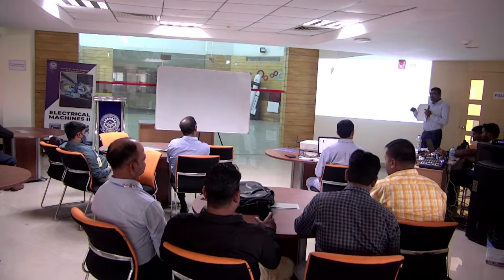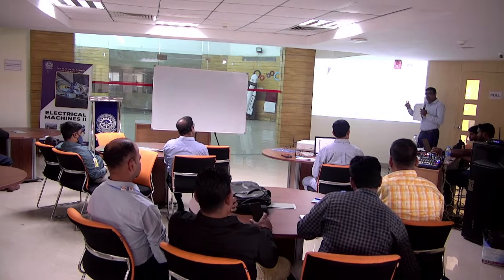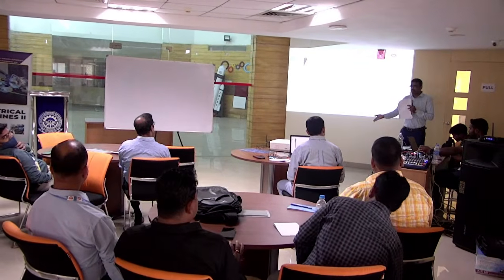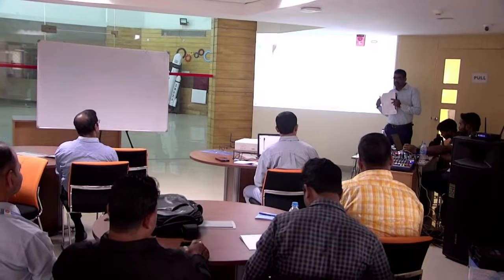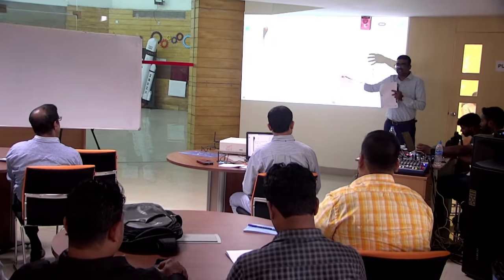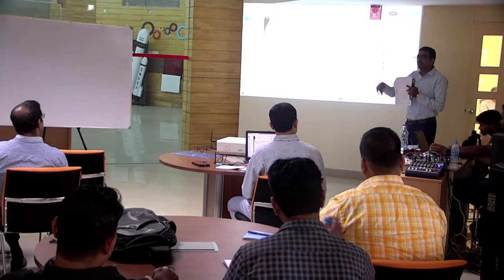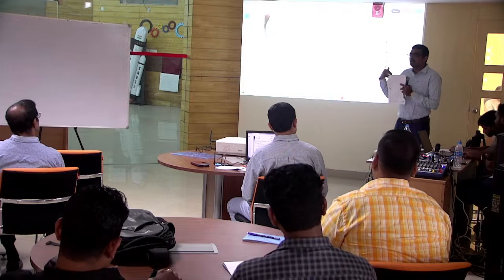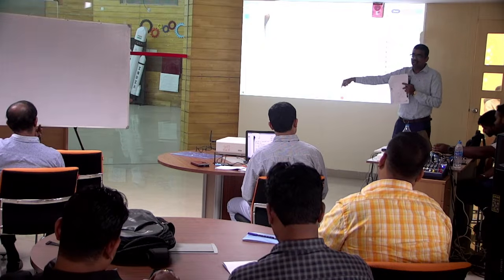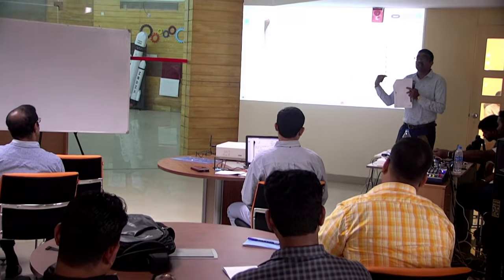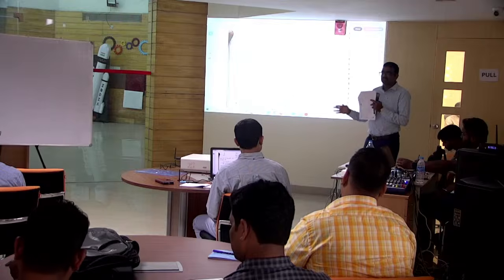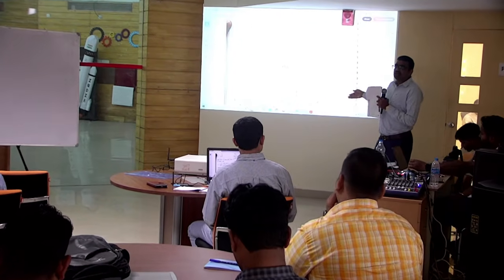The electromagnetic torque produced by this synchronous generator inside the armature will be opposite, just like a DC generator and DC motor. In a DC motor, we get a back EMF: we give the supply, and it induces itself an EMF which opposes the supply, say EB. EB is nothing but EG in the case of a DC generator, Z phi P N by 60A, and both are ideally equal. Similarly, in a generator, motoring action also takes place. We give the prime mover input to the generator, but inside the machine, a counterpart of that applied torque gets induced, which is the electromagnetic torque. In a motor, generator action takes place. In a generator, motoring action takes place. There we call it back EMF. Here we call it counterpart torque.